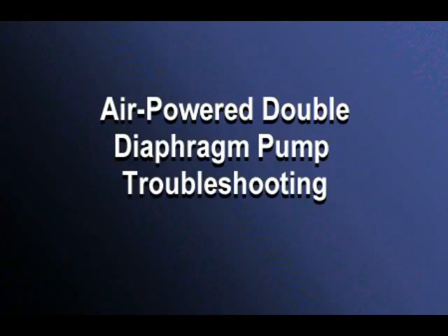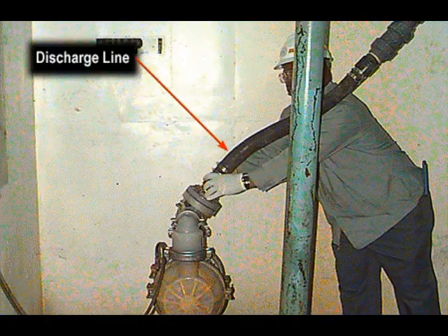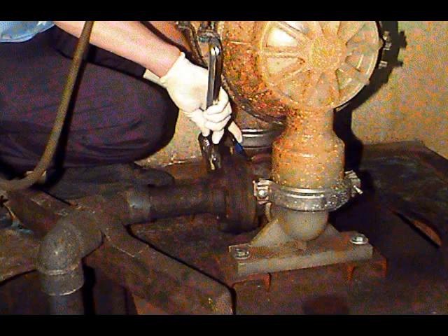While the pump manufacturer should provide more detailed information, here is a general troubleshooting guide for the air-powered double diaphragm pump. Problem: no feed. Probable cause: it may be air-bound, in which case loosen the discharge line to vent air. For acid pumps, open the bypass. Set the feed control to maximum. The cause may be air leaks. For this, tighten all suction line joints.